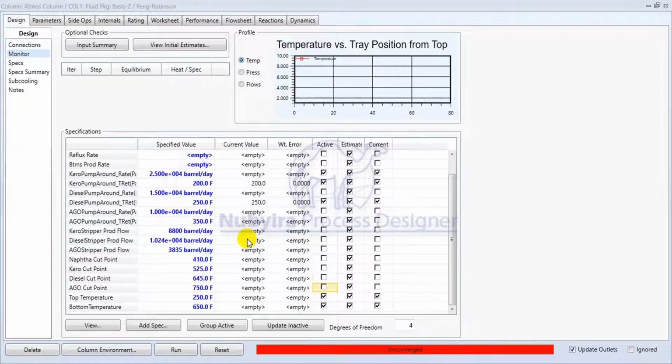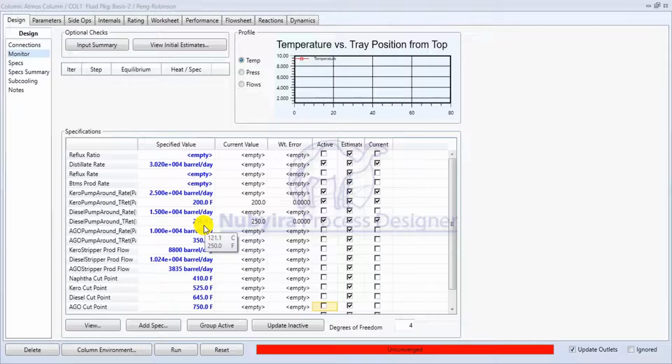So to know the spec to choose, most of these, because I'm using different crude, and these cut points, it's just the distillation cut point of the product specification. So I'm not going to be using this spec first, because I want to be characterizing the crude based on the fixed operation parameter for the column. I'm going to be doing a fixed operation parameter, like the pump balance, you're going to be having a fixed rate, the temperature and everything, you understand, and the reflux ratio, the distillate rate, you understand. So I'm going to start from there.